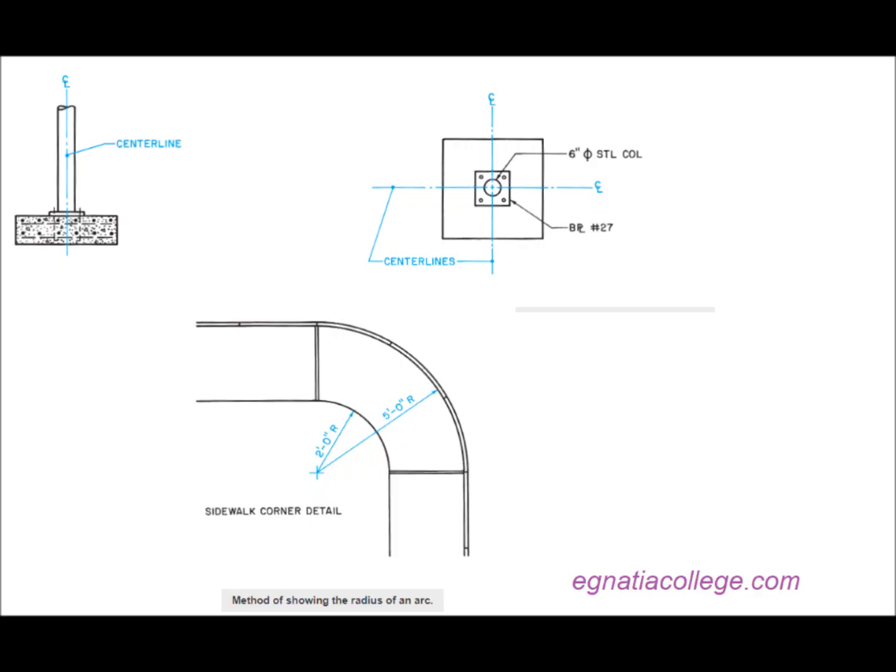The radius of an arc is the distance from the center to the edge of the arc. On construction drawings, the center of an arc is shown by crossing center lines. The radius is dimensioned on a thin line from the center to the edge of the arc. Rather than clutter the drawing with unnecessary lines, only the short, crossing dashes of the center lines are shown. If the center lines are needed to dimension the location of the center, only the needed center lines are extended. Leaders.